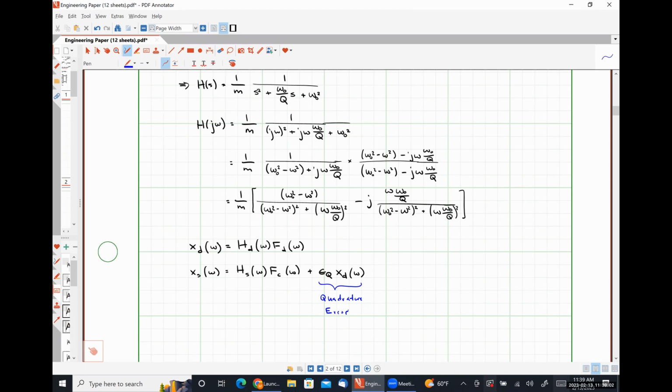And this quadrature error arises due to manufacturing limitations. So effectively, we are expecting our vibrational mode, our drive mode, and our sense mode to be perfectly orthogonal to each other. But what if the reactive ion etching or whatever that we use to fabricate our springs makes one of our springs slightly more stiff than the other ones?